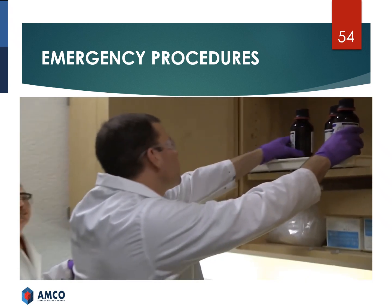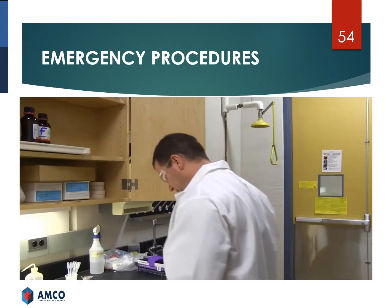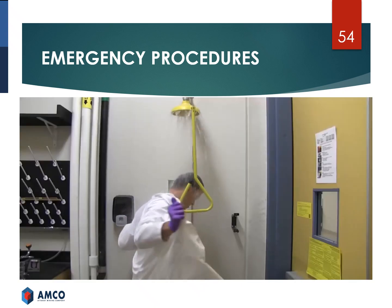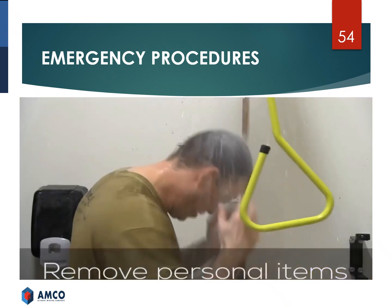If you are exposed to a large volume of hazardous chemical, use the safety shower immediately. Pull the handle to activate the shower. Remove contaminated clothing, jewelry, and shoes.